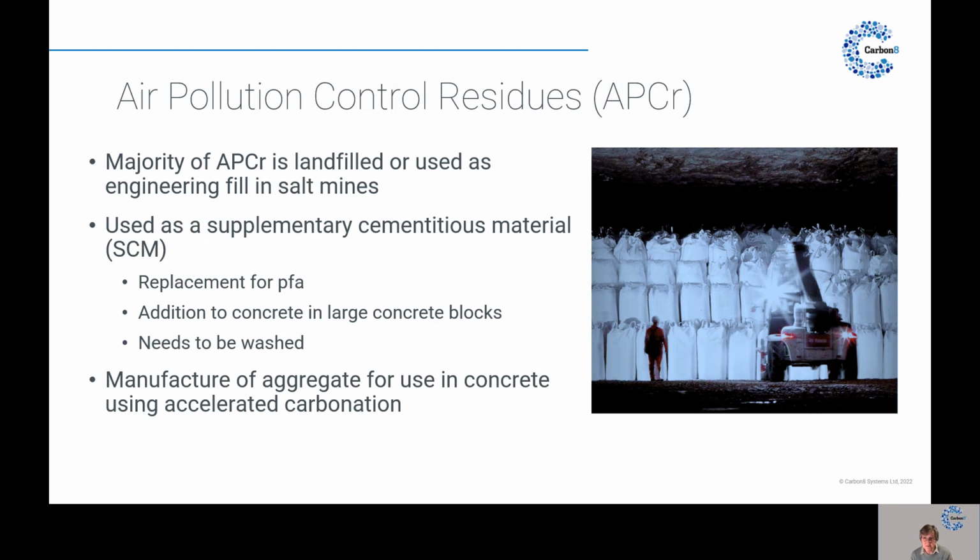A company in Wales is washing APCR for then inclusion into large concrete blocks. Both these solutions presumably required the removal of the chloride, and certainly the system in Wales involves washing the APCR before it's included in the concrete blocks. So you have 2 problems. One is drying of the washed APCR before it can be used, and also disposal of the wash water that is alkaline and contaminated with heavy metals as well as chlorides.